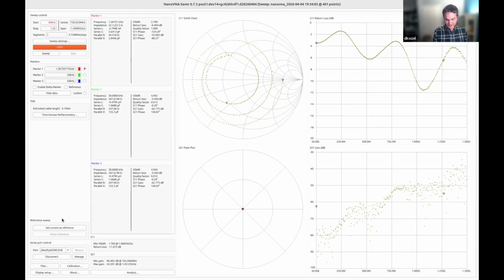You should be calibrating a NanoVNA at least every day that you're using it. You need to recalibrate it every time you change your frequency range. And if it changes in temperature by a bunch, if you go from a cold house to hot weather outside, up on a roof, or you leave it out in the sun, all of your phase information at least is going to become garbage.